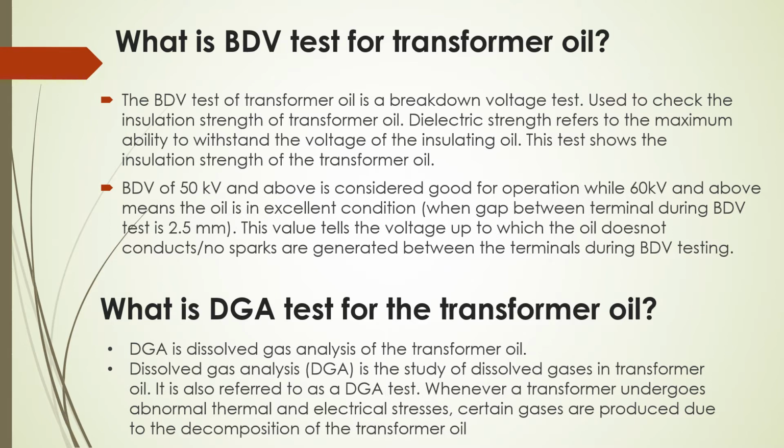The gap between terminals during BDV test is 2.5 mm. This value tests the voltage up to which the oil does not conduct or does not create any spark between the terminals during BDV testing.